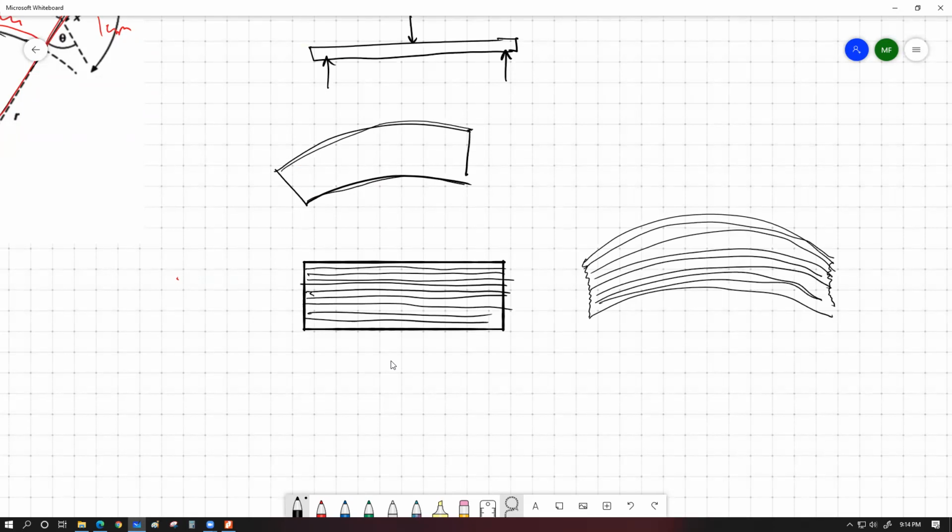What is the advantage? The advantage is that whenever we are slicing up the whole thing into such smaller pieces, we're allowing these individual layers to have a little bit of sliding across each other. Here, there was no sliding allowed. All of the layers are practically stuck with each other. That's why the whole thing had to bend, and we had a pretty large angle produced over here.